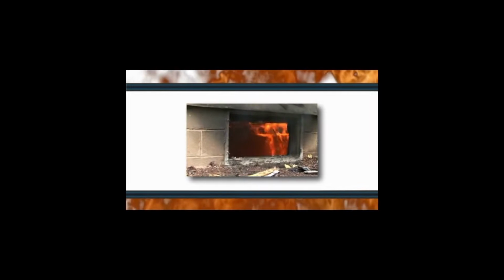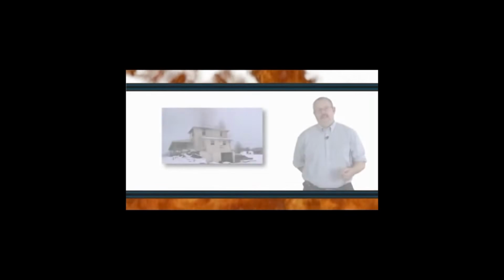A basement fire has always been a heavily ventilation-controlled situation because it's very difficult to ventilate below grade. Usually the windows to the area are very small. These are always very difficult, hot, smoky fires. Often there are interior stairs. However, if there is another entrance other than the interior stairs, that entrance is preferable.